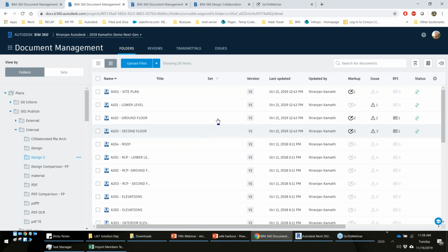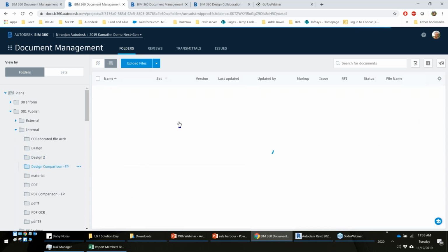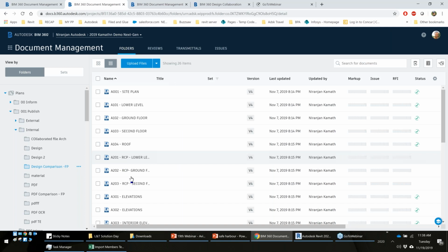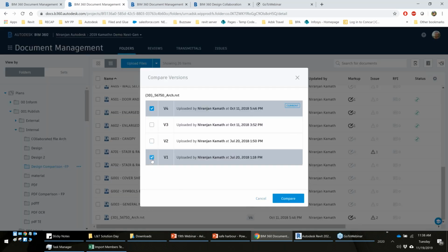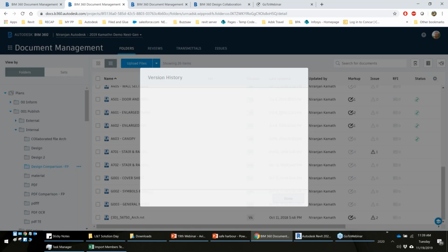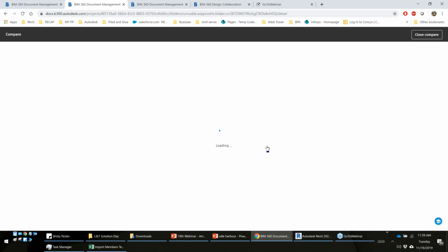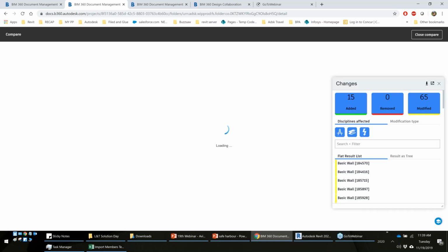So let's talk about the other benefits that we get. Whenever you save a file, it automatically keeps updating the version. Every time a file is saved or synchronized, it keeps a version. Now these versions that you have, you can compare by clicking onto this version button. From day one, you can view how many versions are created, select any two of them and hit compare directly over here. Now this will list down all the items that have been created new, which have been deleted, and which have been modified. So it gives you a complete list of comparison between these two versions.